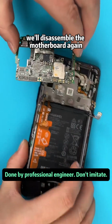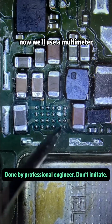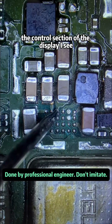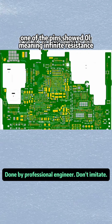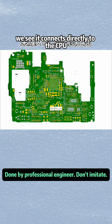We'll disassemble the motherboard again and remove the display IC once more. Now we'll use a multimeter to test the resistance of the display IC's bottom pins. The control section of the display IC is directly connected to the CPU. After testing resistance, we found an anomaly. One of the pins showed OL, meaning infinite resistance. Checking the schematic, we see it connects directly to the CPU.